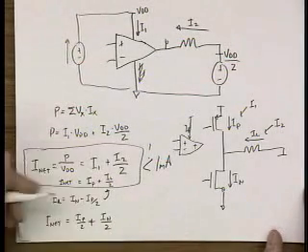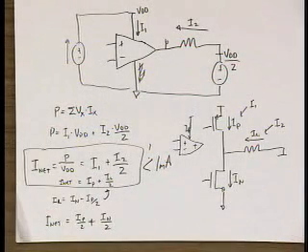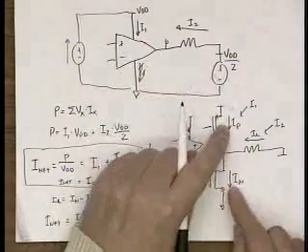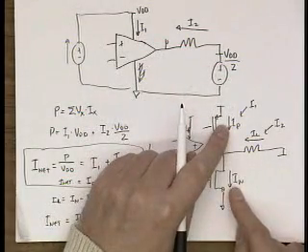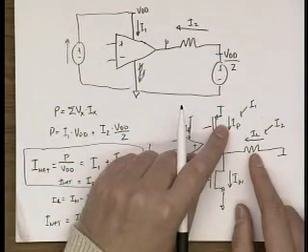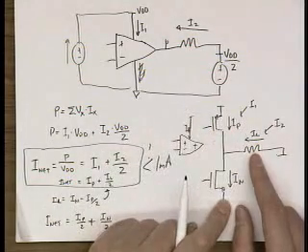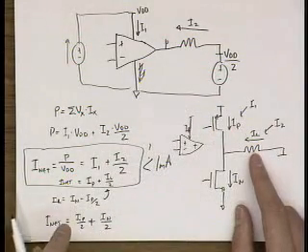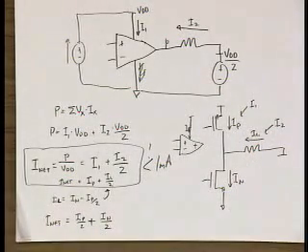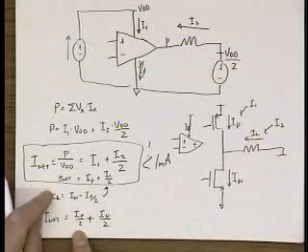This should say plus, but it is over 2. Because IL, if IN and IP are exactly equal, and therefore IL is 0, what's the net current consumption? The net current consumption is IP or IN, right? So if we were to say IP plus IN, that would be 2 IP, which is wrong. It's off by a factor of 2. So this is the correct answer.